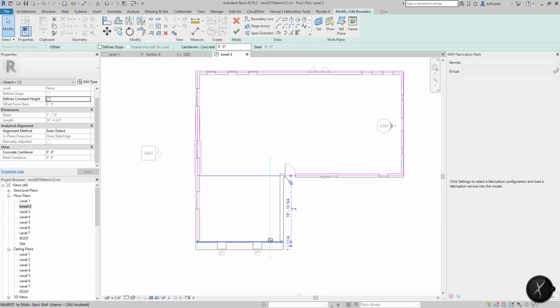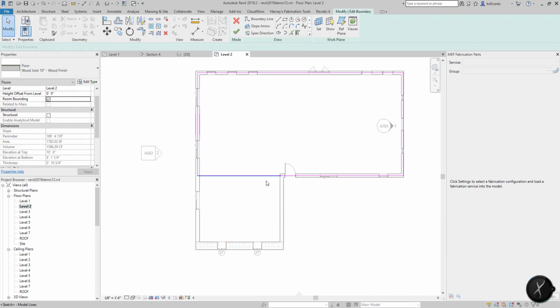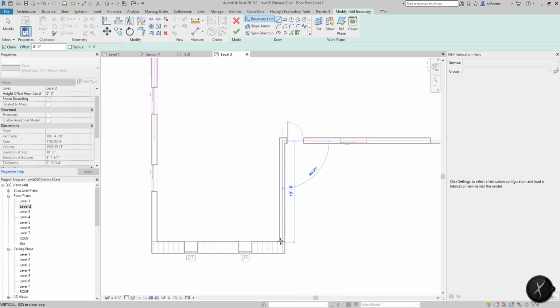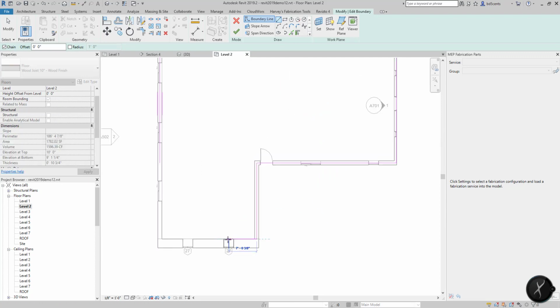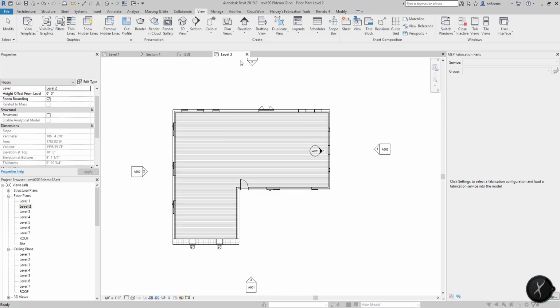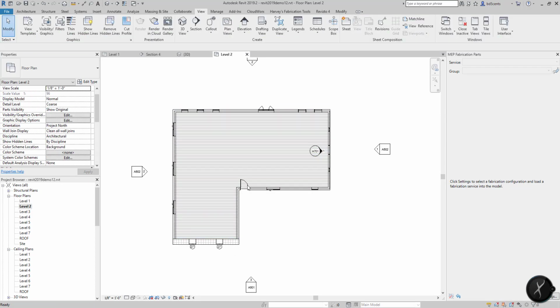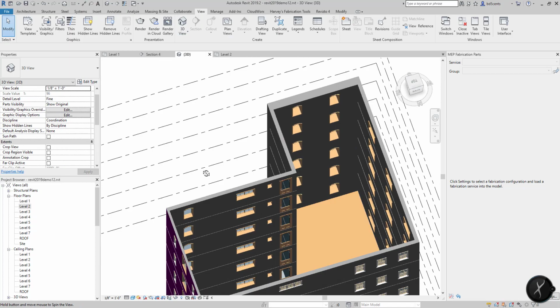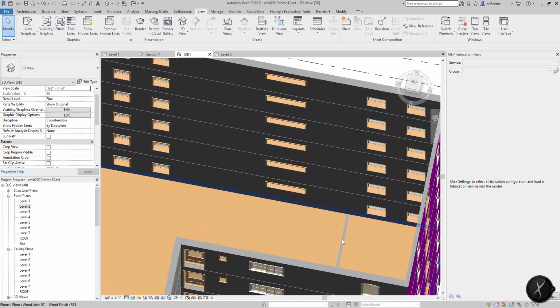So what I could do is just drag this down. I actually can't drag it down. I have to delete it. What I'd have to do is either pick the walls or draw where I want those walls to be. So I'm just strictly drawing the profile. I'm not freaking out. I'm just kind of doing a workaround. I'm going to hit TR to trim these. Once those are in, I'll hit finish, no, and now it's in there. So we have a complete second floor in this building.